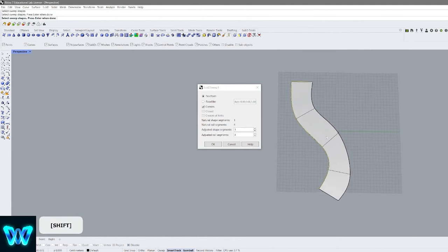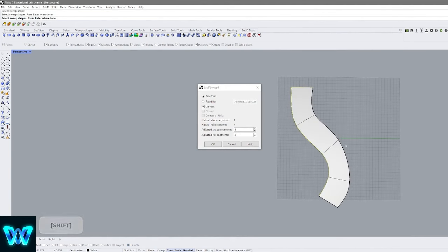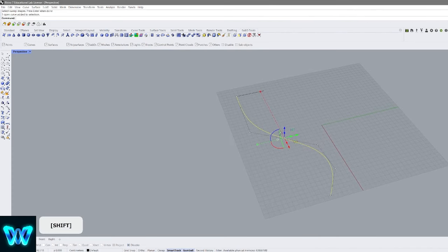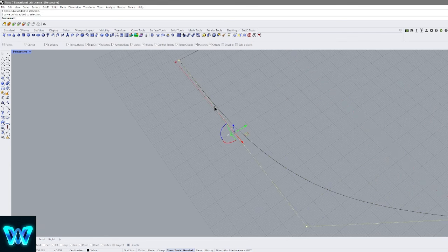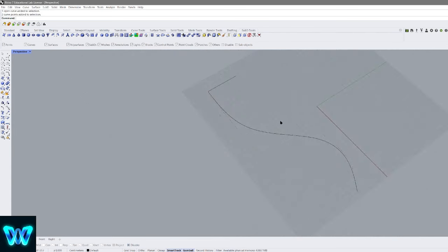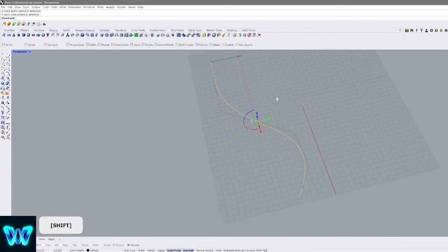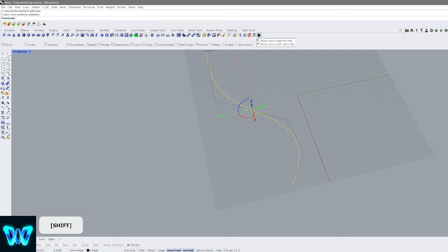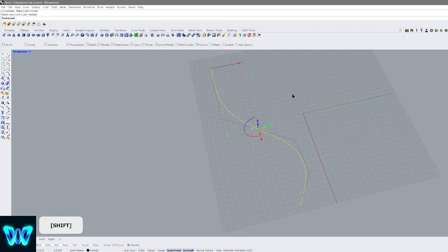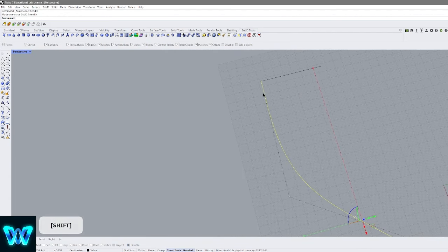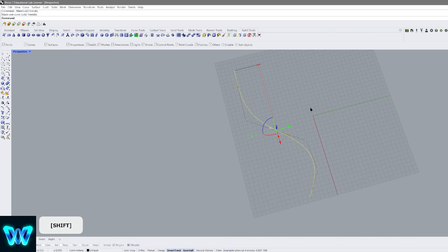And this is very good in order to maintain low poly and in order to maintain the highest versatility to design. At the same time, the moment you create something SubD friendly, which you will see, because at the tips you have this little gray dot. It's kind of invisible, but this gray dot defines when a curve is SubD friendly. If not, you can always just press it again. You can unmake it friendly, then make it friendly again. What it does is that it just pins this last pin straight into this. It makes it a lot easier.